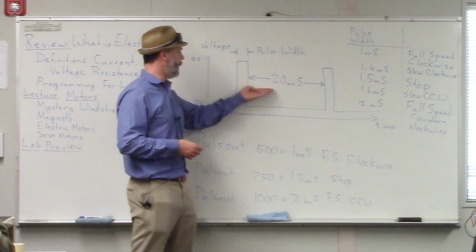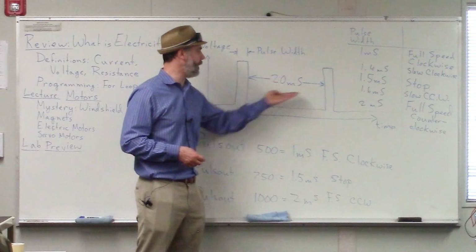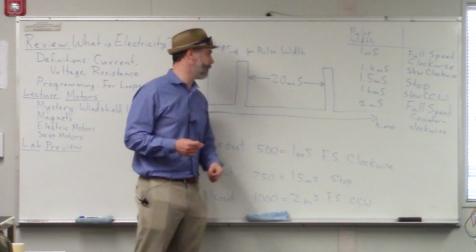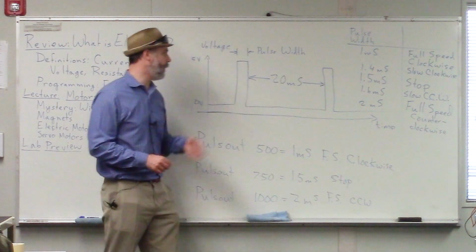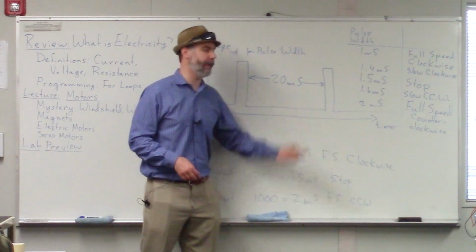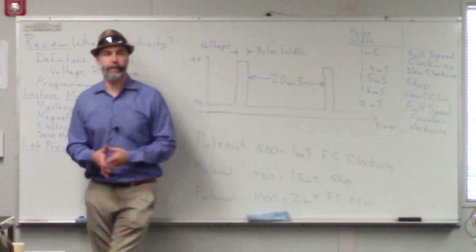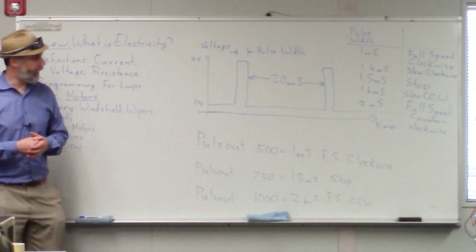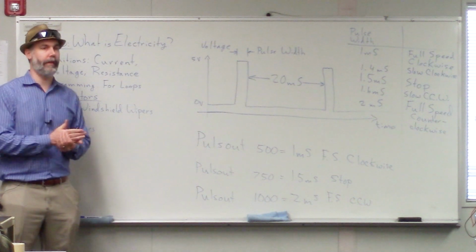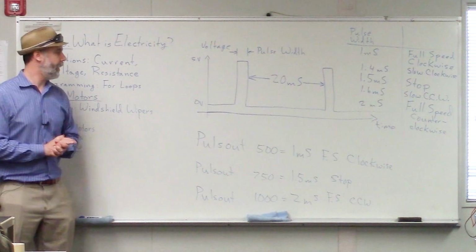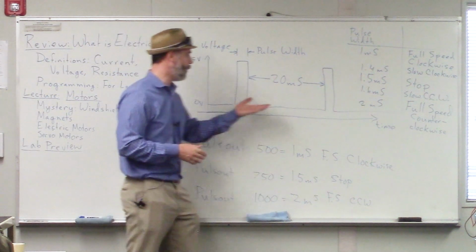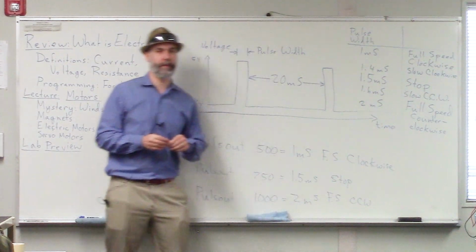But that brings me to a good point. As soon as the motor stops receiving these pulses, it's going to stop turning. So if it waits for like 25 milliseconds and it doesn't get a new pulse, it's going to say, okay, I'm done with my job now. I'm just not going to apply any more power to my motor, and that motor is just going to stop spinning.